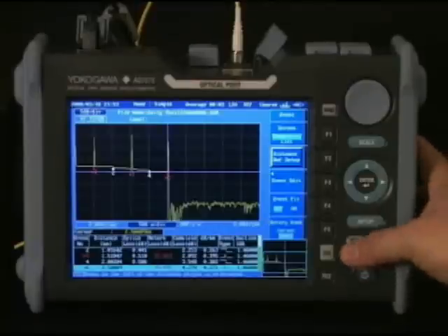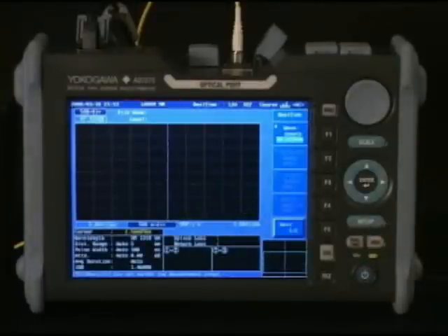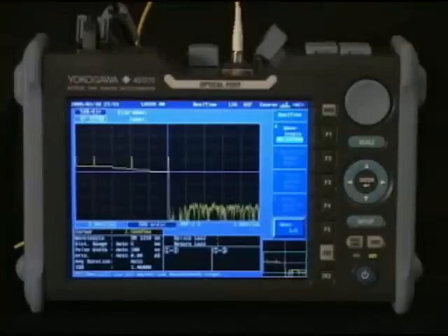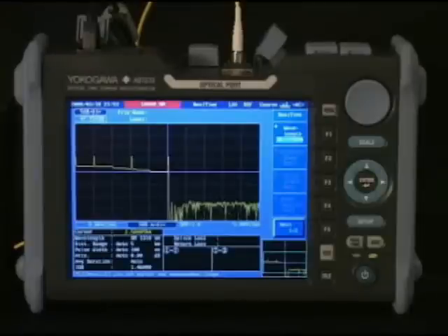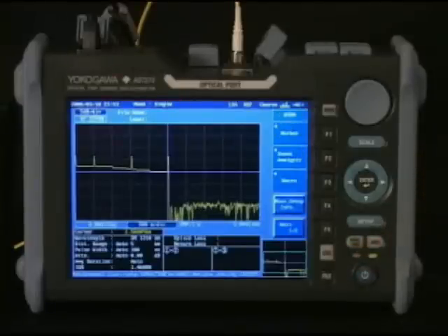The real-time measurement is for active monitoring of the fiber under test. The laser turns on and stays on. This can be useful correcting macro bends in the fiber run, measuring the fiber health, and overall monitoring of a fiber. You must turn off real-time by selecting once more. At the end of the real-time measurement, analysis will not automatically occur like it did in the average measurement.